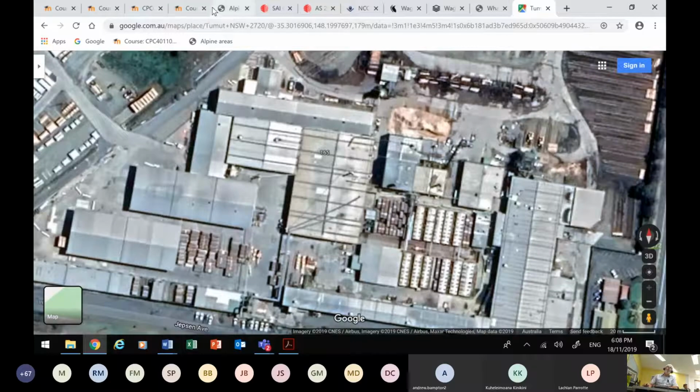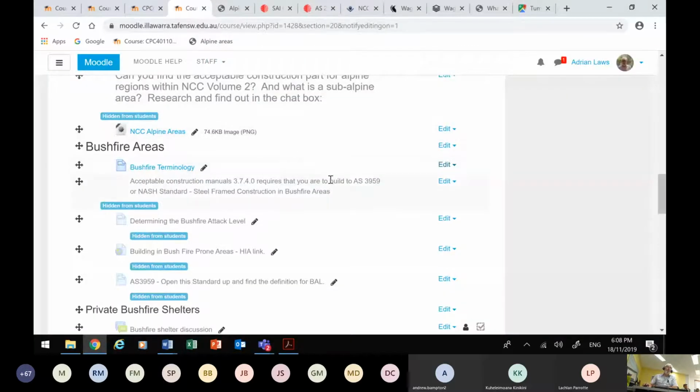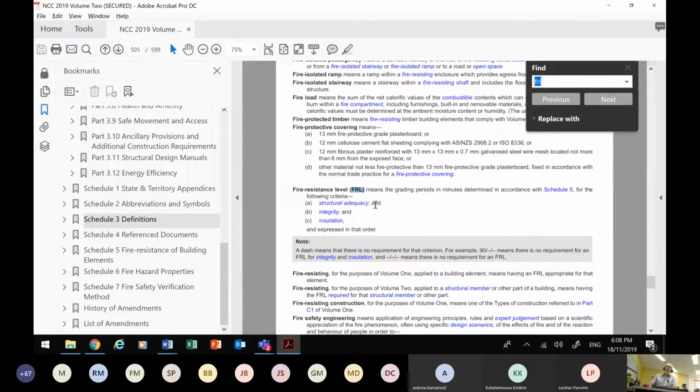It's a lot like trying to burn a big log on the campfire, and it just won't burn. You've just got to keep chipping away and knocking the charcoal off. So that's how they get their structural adequacy for buildings. They use timber to get that layer of char on the outside. It might build up an inch or half an inch of char, and then it'll stay strong, but the fire would not be able to penetrate any further.